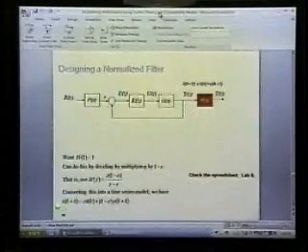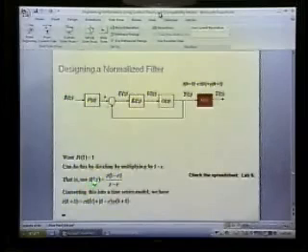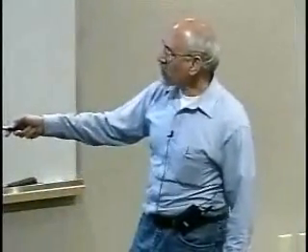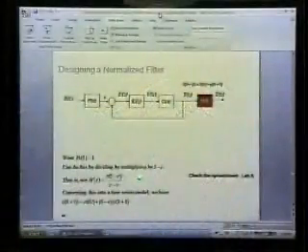And so here's the form we're going to do. We want the steady state gain to be 1. So what we really need is, when z equals 1, we came up with 1 over 1 minus c. We want a 1 minus c in the numerator, because then it goes to 1. Okay, what does that translate into in terms of the filter?